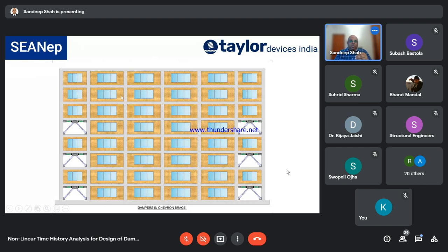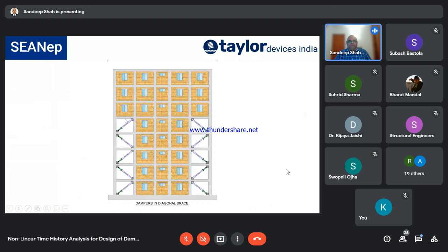So let's say I have friction dampers on the above 3 floors, but I don't have them on the 4th floor, the floor below, and I have them again in the floors below. So this floor is going to become a weak story. It is going to introduce, in this figure, a structural deficiency. Nothing like that with fluid viscous dampers. You can pick and choose the locations where you want to have them. If you want to skip a floor, you're free to do that. You can have them as simple diagonals, if you don't require the dampers on the above 3 floors, because putting in every damper is some added cost.